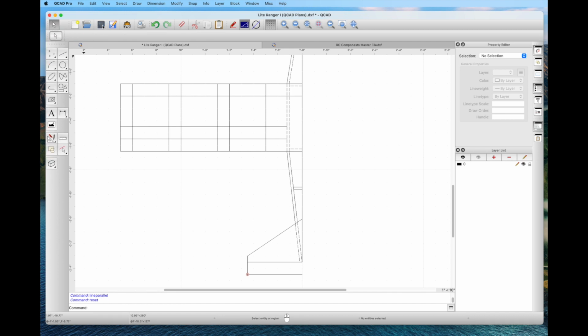That's all done. We go to the breakout segment tool, a very powerful, I call it a trim tool from my TurboCAD days, and just left click, and it just magically gets rid of these extensions even between lines. It's just incredibly useful to use this. Remember, if you make a mistake, no worries, just undo. You'll be right where you were before.